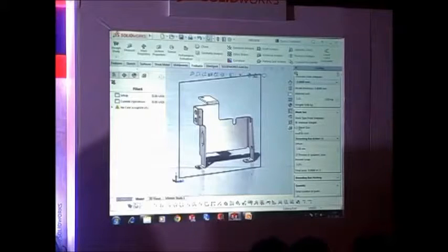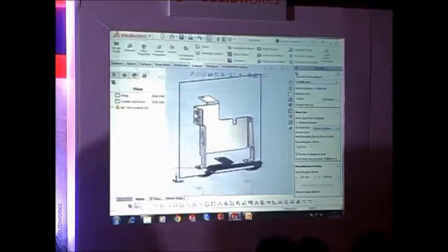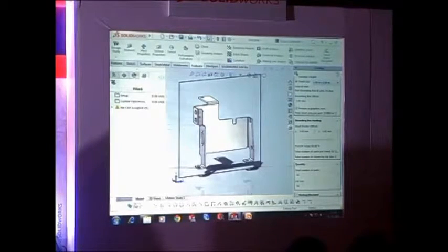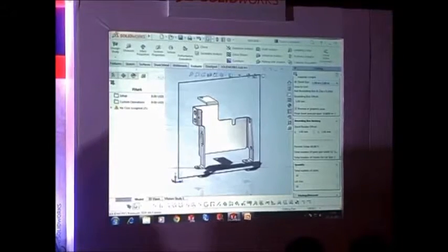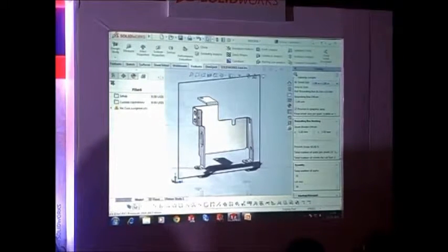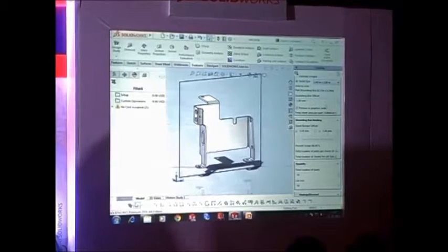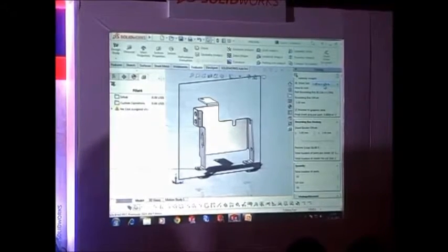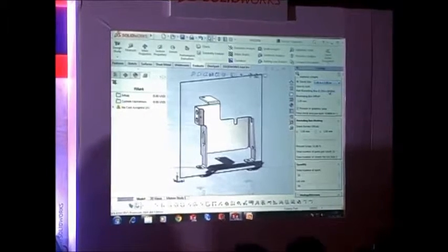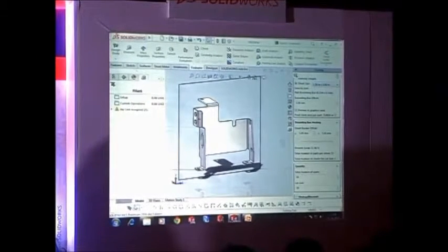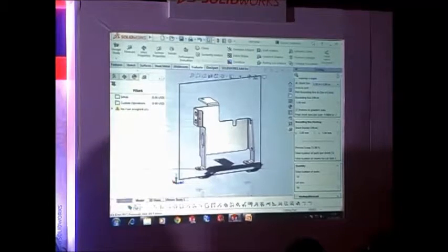Now you can calculate a cost based on sheet size, and SOLIDWORKS 2016 also provides a percentage of scrap, total number of parts per sheet, and number of sheets per lot. Since the sheet size is small, it requires 2 sheets. When the sheet size is large, it requires a single sheet. Not only that, we can also get a visual representation of a bounding box.